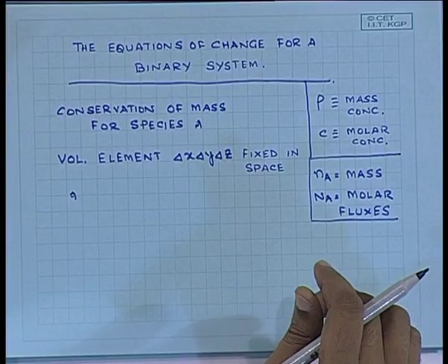Concentration is definitely one of them, but temperature and pressure can also give rise to a change in chemical potential. So, diffusion takes place if there is a difference in chemical potential. All the factors which contribute to a change in chemical potential can in turn induce flow. You may have concentration equality, but temperature inequality. That will give rise to a flow. These are interesting effects and they are known as Soret effect, Lewis effect, Marangoni flow, etc.